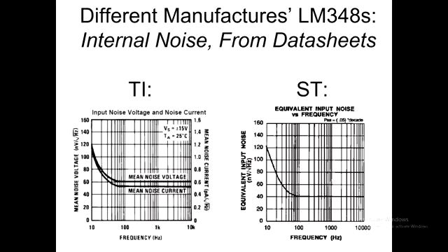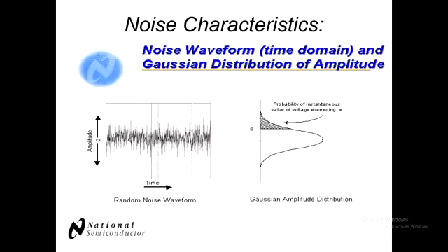Five three what? Okay, picoamps per square root. You're saying it's 5, yeah? Okay, yeah. And be careful again, because you've got to make sure you're not looking at a log graph. But we're not this time. This is log, that's linear, isn't it? Yeah? Be careful of that interpolation of logs that we talked about this morning.